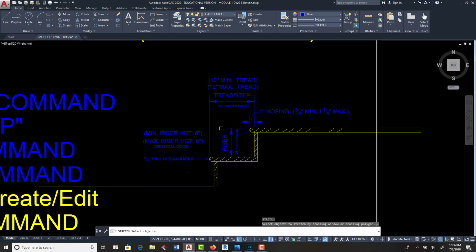This is a floor, and this is a floor, and there's only one tread, but there's one riser, two risers. There's always one less tread than riser. So if you have 15 risers, you know you have only 14 treads. So that helps you figure out the math.